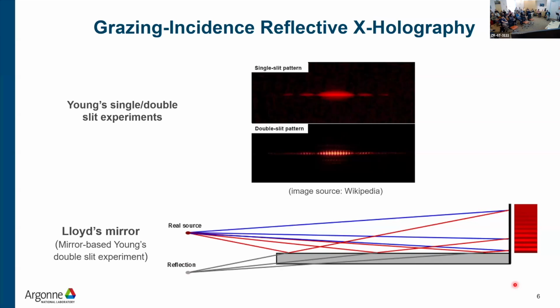So this was actually discovered 196 years ago, in 1830. It has a bunch of applications nowadays. For example, you use this in UV photolithography. This method has an advantage over a regular photo mask, because if you use a slit to do lithography and you want to make a small feature, you have to increase the slit distance, right? By that you lose a lot of flux, so the power is low. But with this, the only thing you need to do to make a small feature is raise the source height to keep all the power. So this is an advantage.